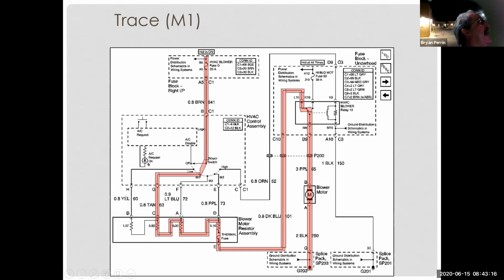So if I go to A, should I have less voltage? You have a resistance. Yes. Yeah, because I went through a resistor, correct? Yes. And then if I come down to D, I'm going to have even less voltage because I've gone through 2 resistors. And E, I have even less voltage, correct? Yes. Correct. Okay. So now, how much voltage do I have at B?